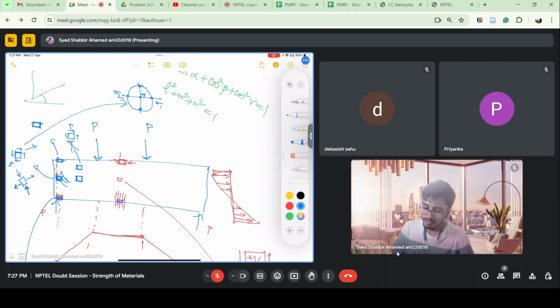So that's why here, because the shear stress is maximum, I might get cracks like this. In between, crack directions will be something between 0 and 45 degrees, like this. So this is how crack directions will look if I take a concrete beam.